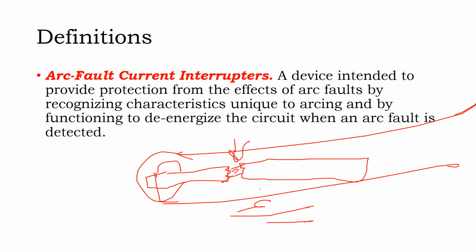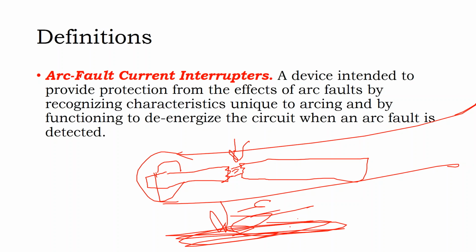Maybe it's connected and you get full current, and then it changes, and the resistance goes way up, and it starts to heat up, and it heats up this PVC and melts it onto the rooftop and starts burning your roof and starts burning your building down. That's different than a ground fault, and it's detected differently than a ground fault.